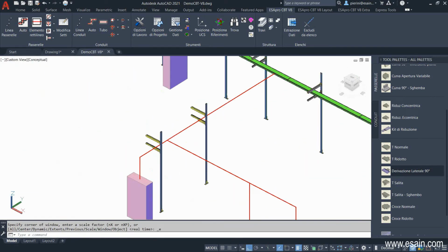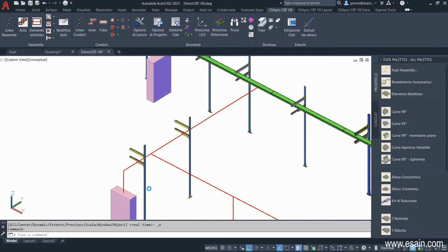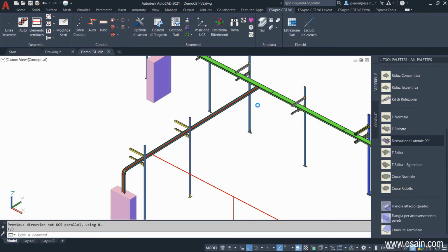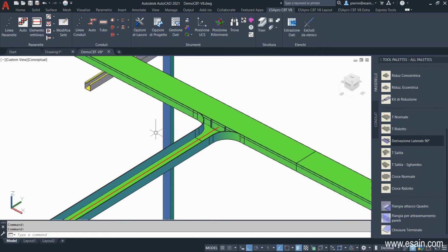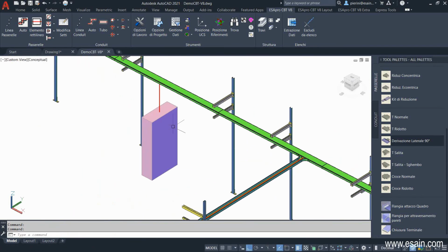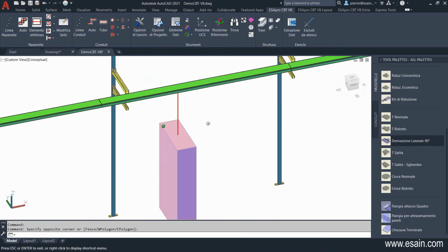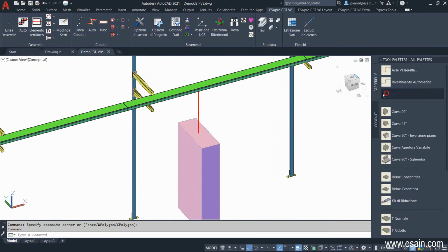With the same procedure, we dress the branch that leads to the motor panel. Starting point, direction, and connected junction. We add one last straight element to connect the middle panel. Straight element, starting point, ending point, direction.